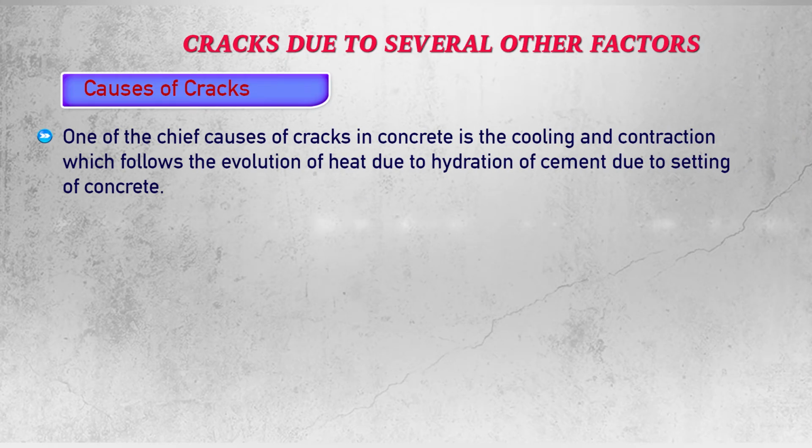Now, let us see cracks due to several other factors. What are different causes of the cracks? One of the main causes of crack is the cooling and contraction which follows the evolution of heat due to hydration of cement due to setting of the concrete.